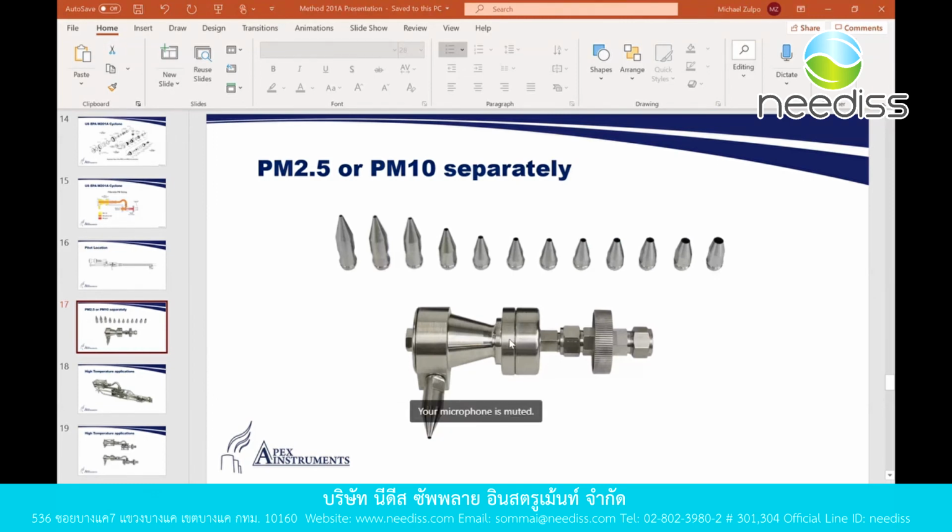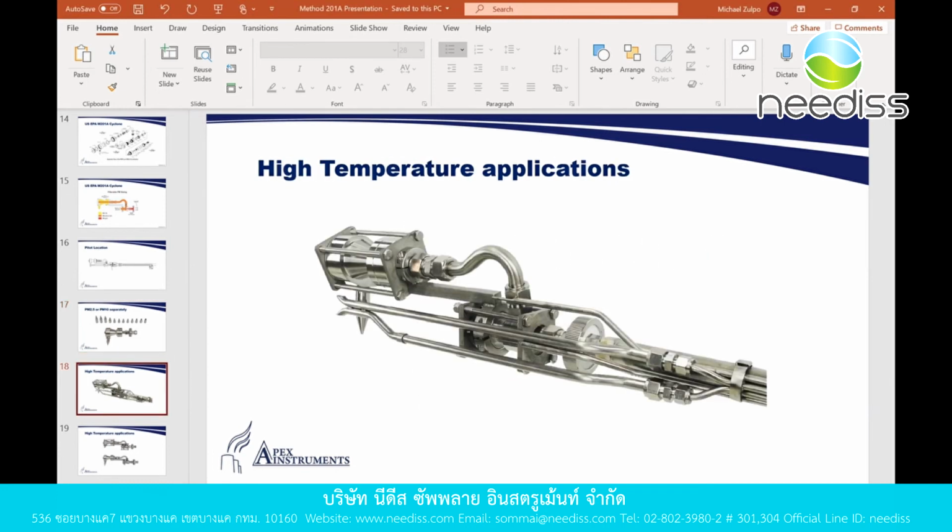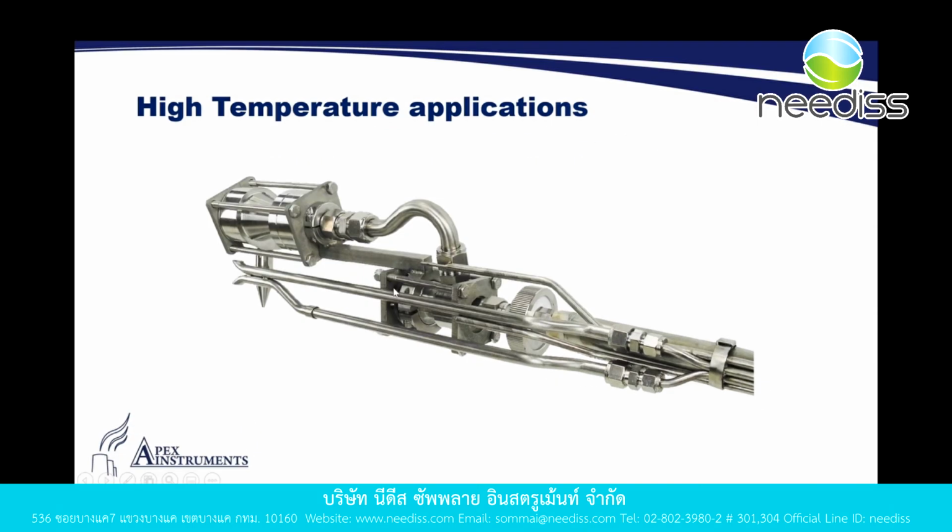There's threads here like you would see on a glass bottle or a jar or what have you. When those threads get exposed to very high temperatures, they can melt together. The threads can become what we say in English, galled. And it's almost impossible to then remove them and separate those two pieces of stainless steel.